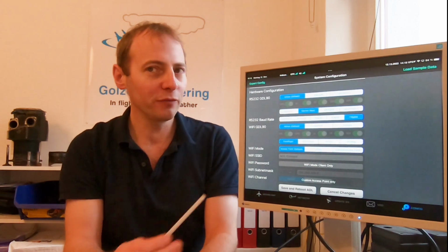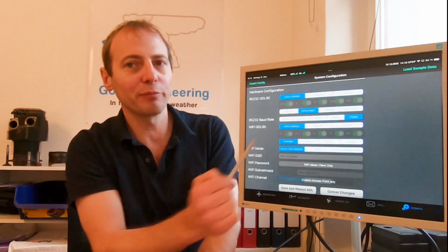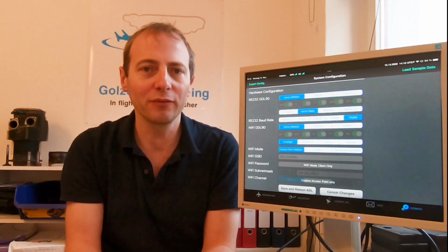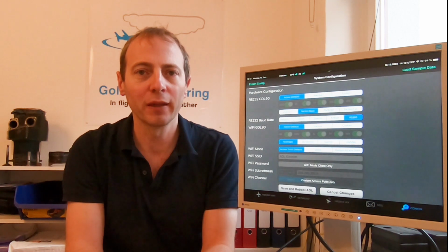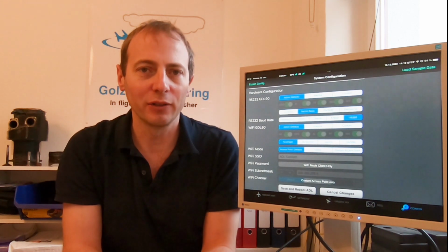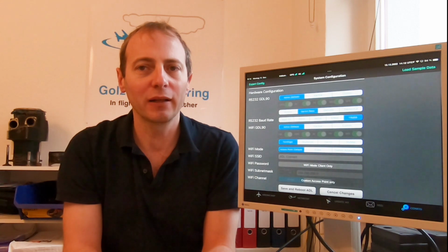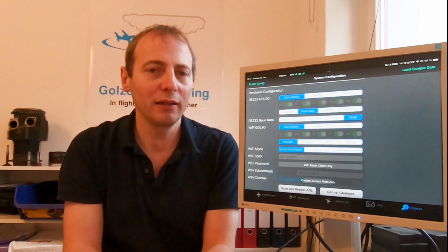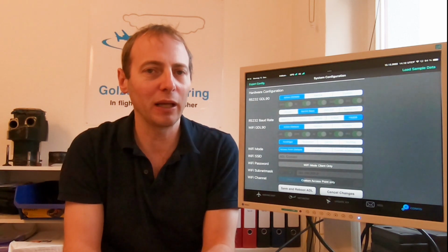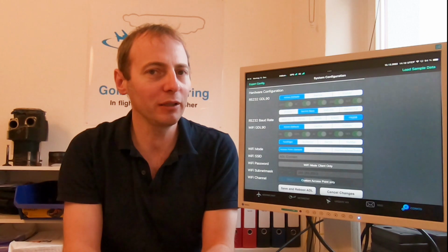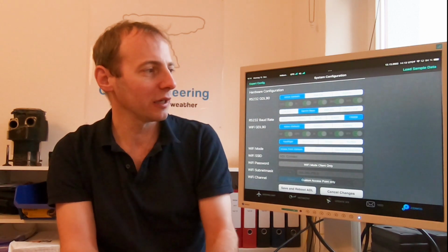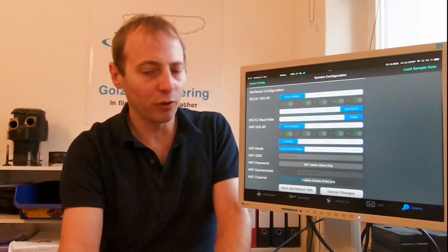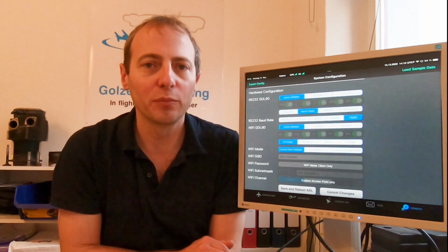And so the most common format you will probably want to choose is the Garmin Basic. That's a format which is suitable for most Garmin devices, and it contains the radar picture and METAR and TAF. The strikes and the cloud tops from the satellite are not included in this data format because many Garmin devices cannot display this data. If you have a very modern Garmin device which can display this data, you can account for this, switch over to the Garmin Full format and then output this data.